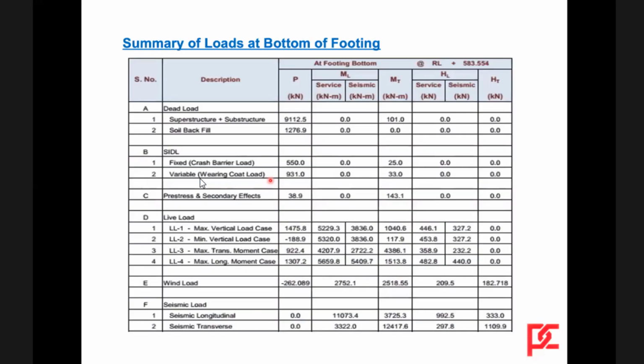Then these are the various load combinations for the footing at the bottom of the footing: the dead loads and soil backfill, SIDL, secondary effects due to pre-stress, and then live loads. In the live loads, the live load combinations which give maximum vertical load, maximum transverse moment, and maximum longitudinal moment are tabulated here. Then wind load, seismic load.